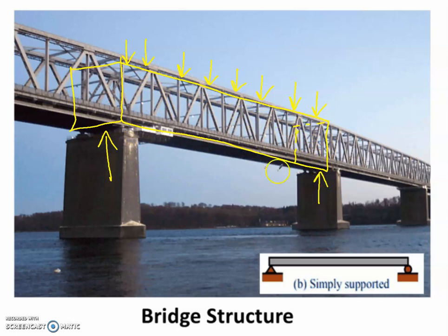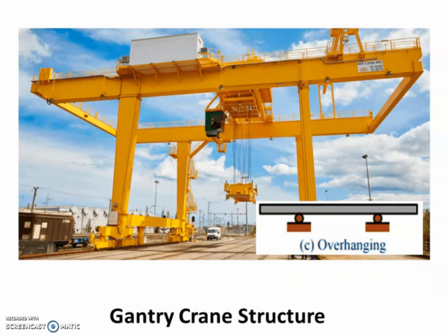We'll also get point loads occurring. So say it's a vehicle bridge. If a lorry goes over it, as the lorry goes along, wherever the lorry is, it'll be a point load. You might have some cars, a bus, whatever. So you'll have point loads as well. So this brings us on to symbols, and we'll be looking at those in a couple of slides.